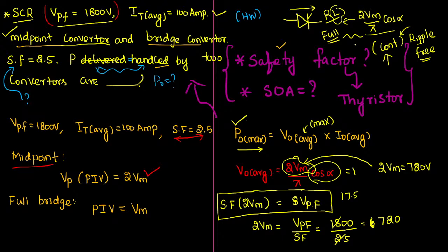That's why in all chopper circuits you can observe your circuits will be designed with the help of inductors and capacitors. You can recheck now, because those two are taking responsibility to produce ripple free voltage and ripple free currents. Got it? So here they haven't given any information about the type of the load or nature of the current on the output side. So by default, you have to assume that the output current is continuous. When the output current is continuous, then the average output voltage of the full bridge converter will become 2 Vm by pi cos alpha only. Okay, these things are by default.